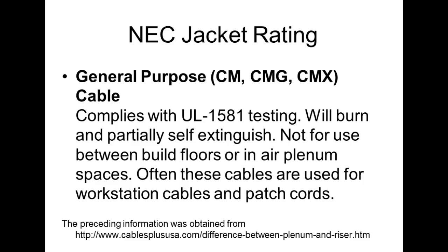So I might specify a CMX cable, and then say, well, I can't get these or I can't find it, and you can look it up in that chart, and it would tell you what other ratings on those jackets you could use. And that's up there. By the way, I found that the other day and put it up on the site. In fact, all this was defined from where?